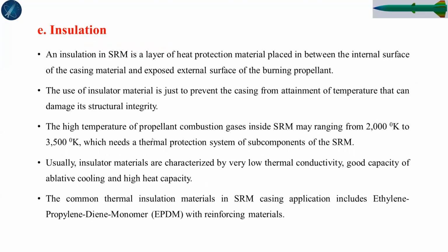The next important component is insulation. Insulators are materials which protect against heat transfer from the motor chamber to the external surface of the rocket itself. Insulation in a solid rocket motor is the layer of heat protection material placed between the internal surface of the casing and the exposed surface of the burning propellant.